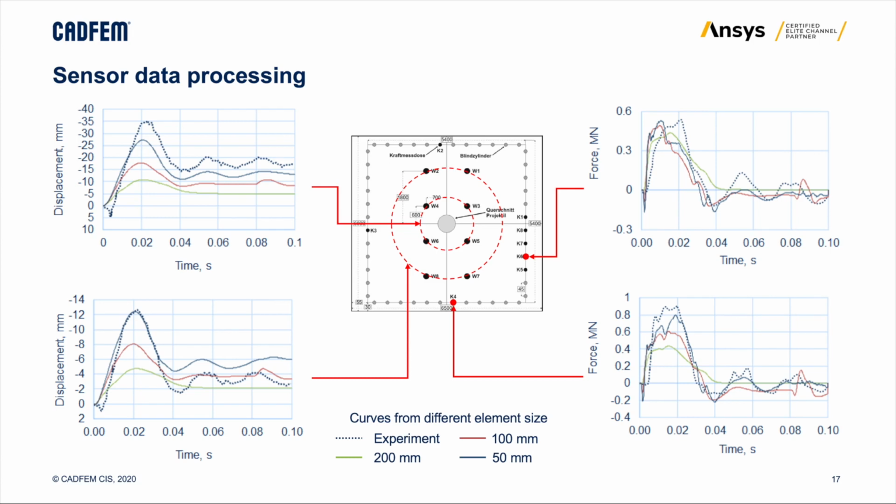The only result that could be improved is the peak displacement in the area near the impact zone, but that could be improved with a new type of mesh and with material erosion. Currently in our model we do not use material erosion and element death.